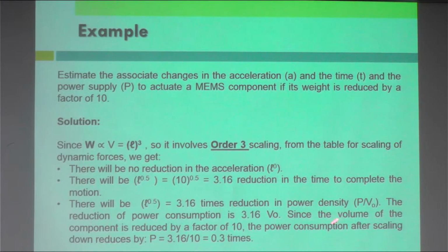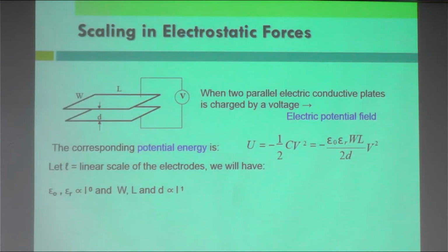So meaning to say, if you reduce the weight of certain components in MEMS, you can reduce the power required by 0.3 times. Okay. So electrostatic force. As I mentioned before, you have electrostatic force for the actuator. So electrostatic force or electrostatic comb drive is normally used quite commonly in MEMS because it's easier and it provides quite significant power to have an actuator.